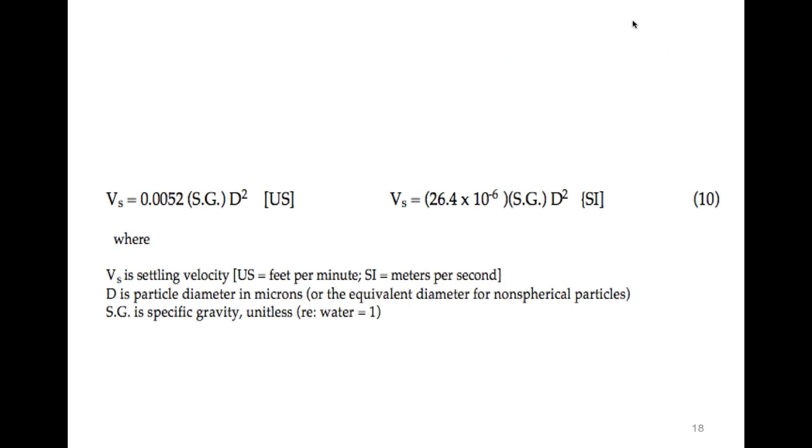One of the other things we're interested in is capturing contaminants. Not all of those contaminants are going to be gases. A lot of times those contaminants are going to be particles. Particles have mass, so we have to understand what the properties of these particles are. And most of the dynamics of small particles, this may come up in other courses, is based on the size. In other words, you're not so concerned about the density of the particle directly. When you're dealing with small particles, you can make a lot of assumptions based on the size of the particle without worrying quite as much about what the real density of that particle is.